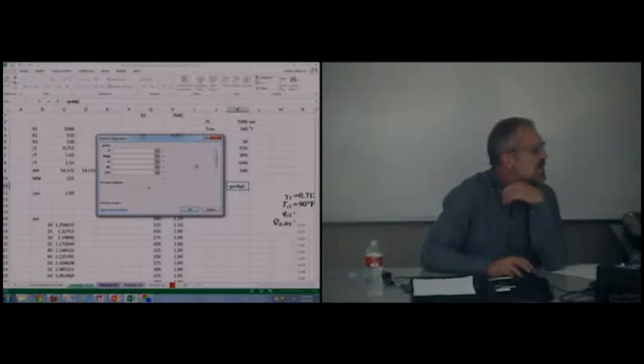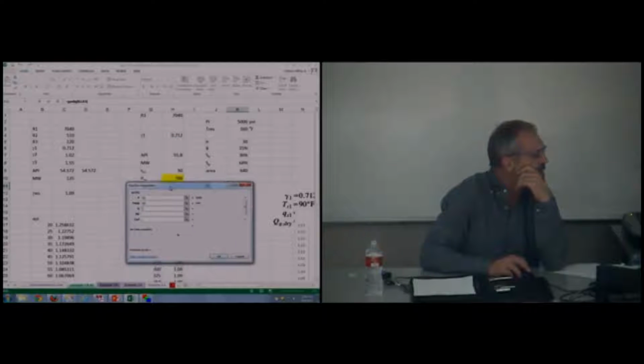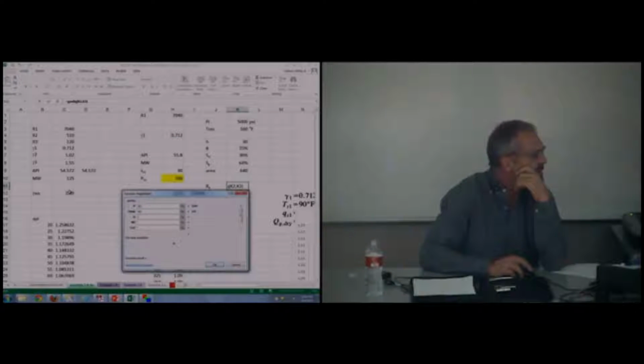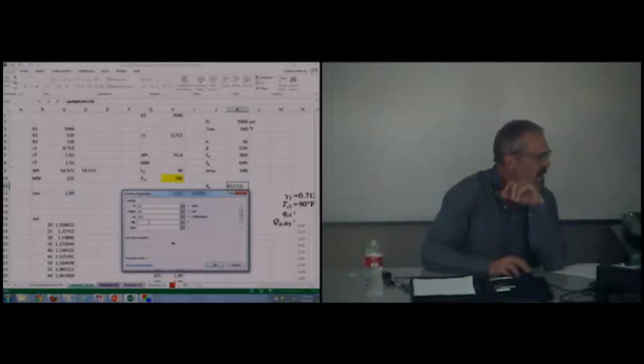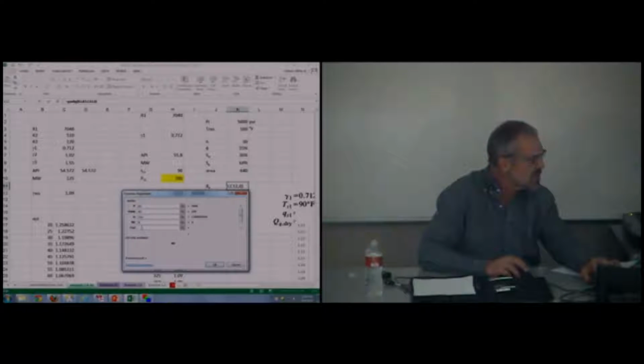Well, it looks like we are, because it's gonna calculate the Z for me, you see that? T-res, that's phi, that's pretty clever here. Pressure, 5,000, temperature, 160. That's G. Gas gravity, okay, we're gonna go with this gas gravity right here, 1.09. It's our one calculated without correlations. And as far as we know, there's no impurities.